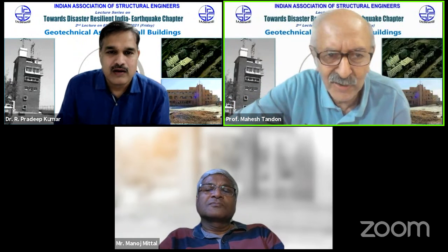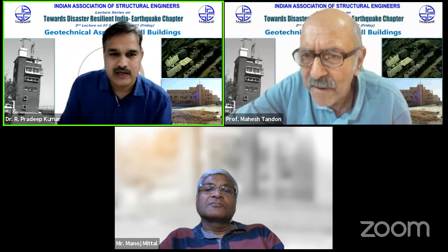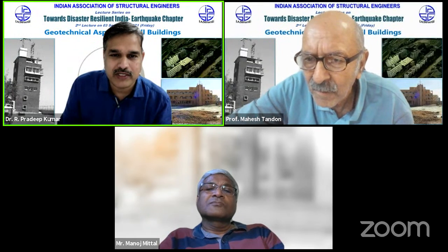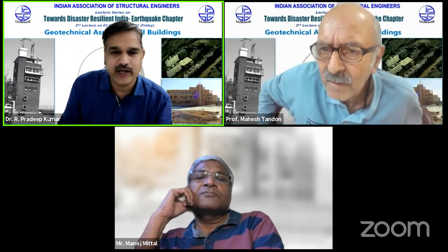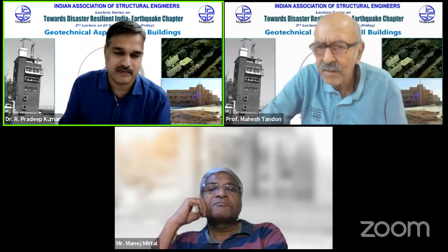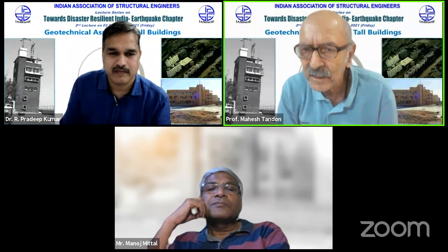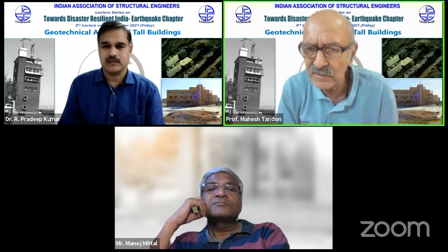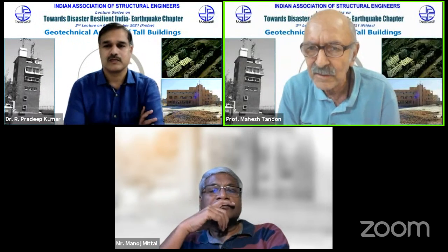Can you just tell me where it is? Is it in the chat? In the chat, sir. What is the question? I think from the bottom, the third question. What can be the remedial measures if a well foundation of a major bridge settled and tilted due to reduction in embedment depth because of plundering of bedrocks? Yes. The raker piles work to reduce further settlement and tilting. This is the situation near Haridwar.